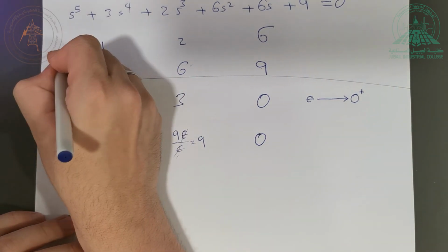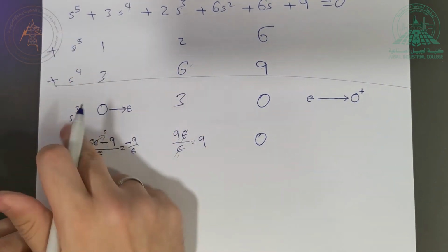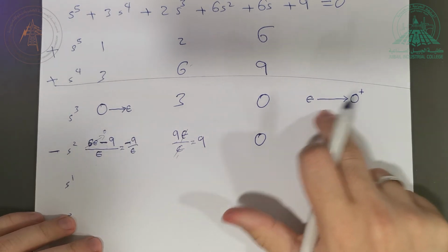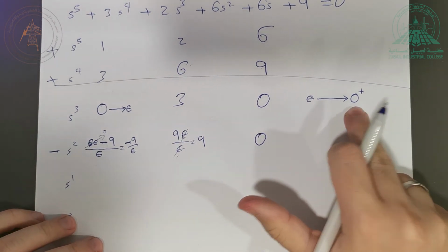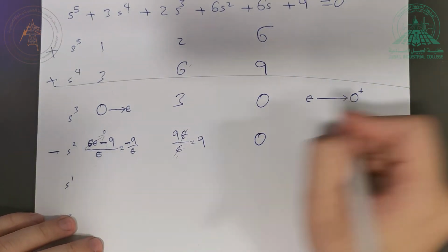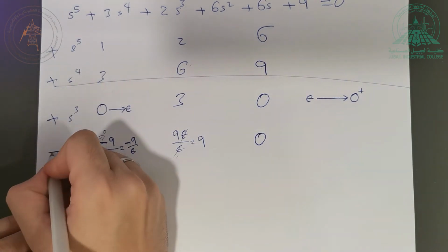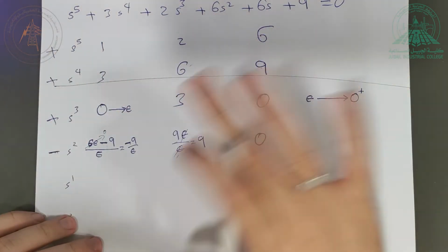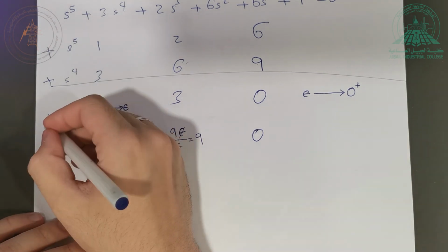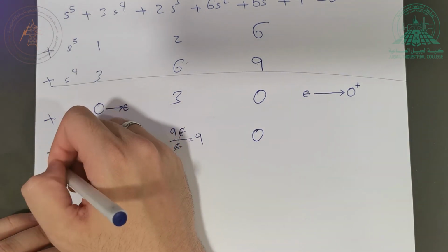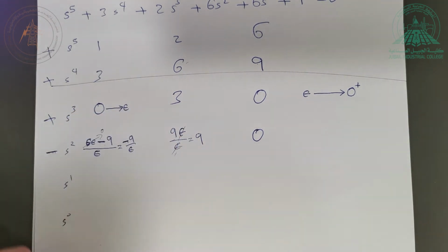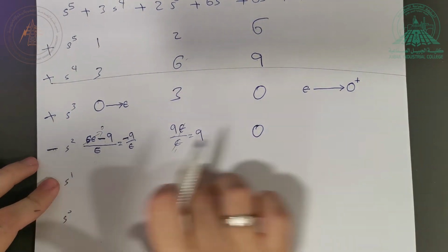The sign here, what is the sign here? It's positive. What is the sign here? It's positive. How about this one? Remember, epsilon is positive. It's a small number, it's almost 0, but from the positive side. Right? So this is also positive. But this one is negative. So I already know the system is unstable. At least I have one change in the sign. At least I have one pole. Right? So I already know I have at least one pole. Now let's continue for this one.